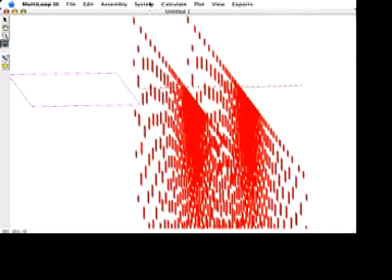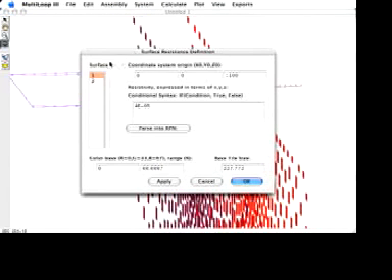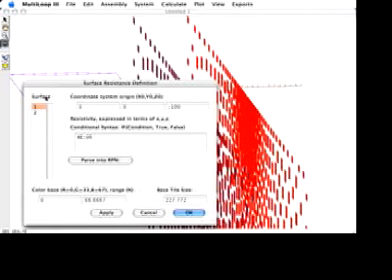Now we're going to define the resistivities on the mesh. To select a resistivity function, click Assembly and Resistance. Here we see the two surfaces that are in the model, surface 1 and 2. Selecting the surfaces will highlight the meshes. Here we can change the resistivity by typing in a new resistivity function. We parse the function into reverse Polish notation, and we can then apply a different resistivity to the other mesh, or the other surface of the mesh. Again, parse it into RPN and apply.